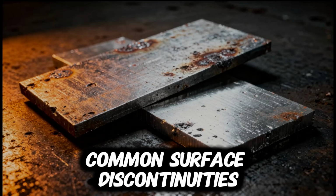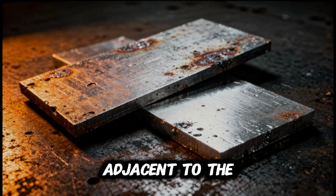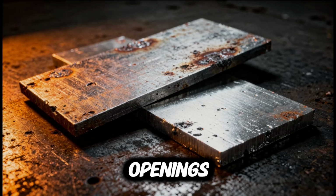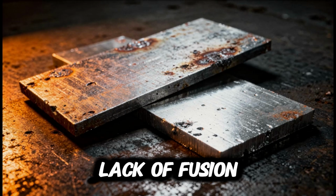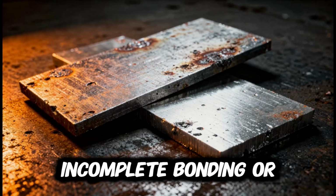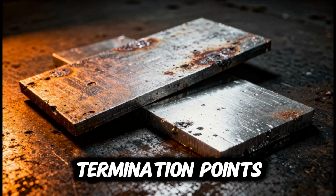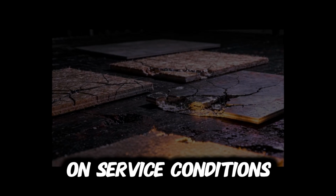Common surface discontinuities detectable by VT include undercut, which is a groove melted into the base metal adjacent to the weld toe; porosity, which are gas pockets visible as small surface openings; slag inclusions, which are non-metallic residues trapped at the surface; lack of fusion, which appears as incomplete bonding or linear separations; and crater cracks, which are star-shaped fractures at weld termination points. Acceptance of these features depends on applicable codes such as AWS D1.1 or ASME Section IX, which define maximum allowable dimensions based on service conditions.